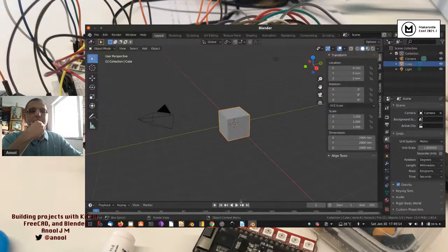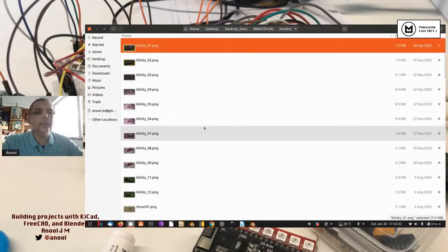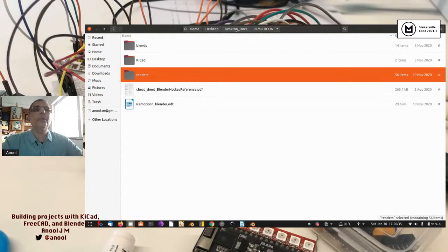But one way of achieving that is to take a standard model that you might have from a KiCad 3D library, like an 8-pin DIP, for example, open it up in Blender, grab logos from Atmel or whoever else, add them to the device and save it as a new model. It's a bit involved in the beginning, but as you keep doing it, you build up a library of parts, so it becomes easier. In the end, you can get some really nice looking outputs from a render.